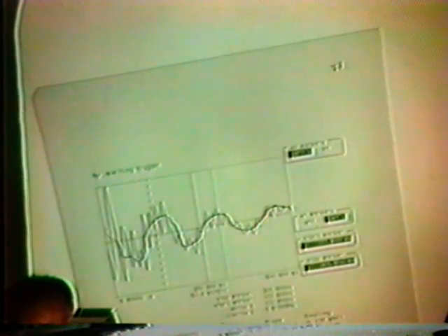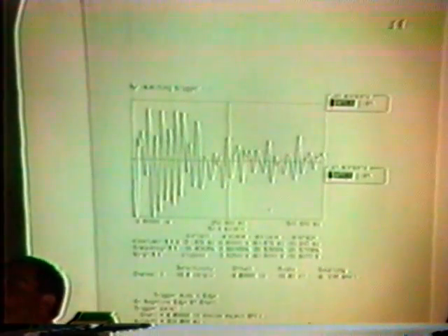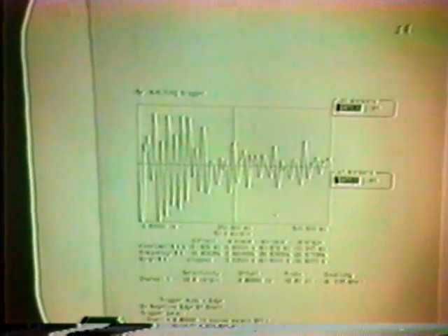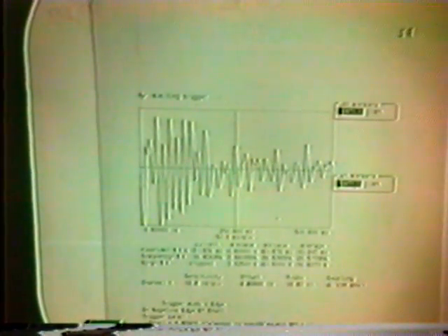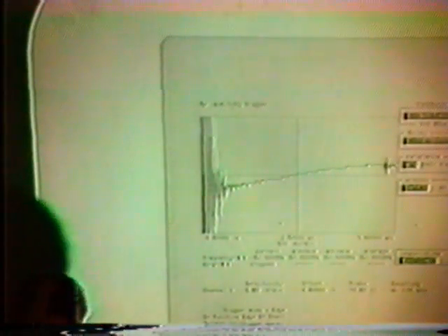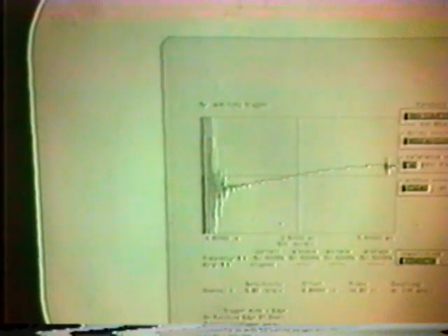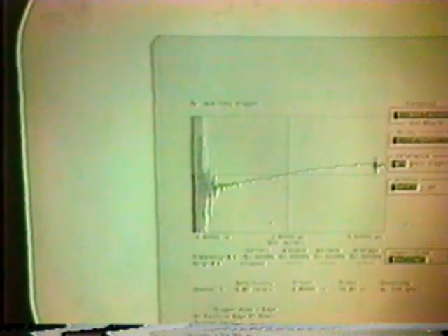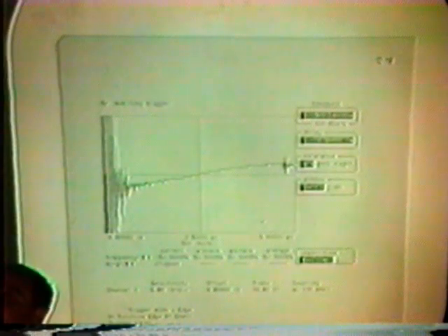In other cases, for example this one, where the ringing frequency is almost not existing, the excess energy is much higher than 200%. And in the first ones, like this one, though the amplitude is very high, the duration is very short, so the excess energy compared to the total energy released from the capacitor bank should not be expected to be very high.